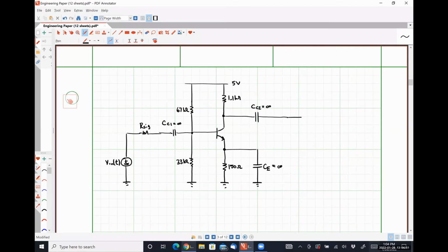It's going to be large for the same reasons. And then we're going to have a particular load resistance. And then our output voltage is actually going to be a combination of a DC signal with a superimposed AC signal on top of it. Okay. So this is what an actual BJT amplifier circuit would look like.